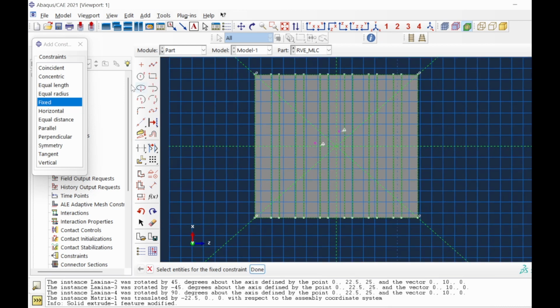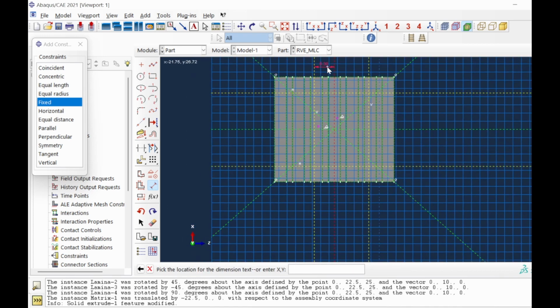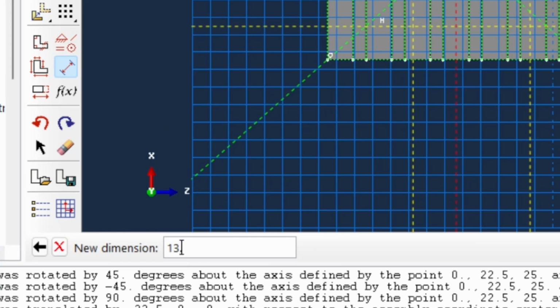Right. So what we're going to then do is to just randomly introduce some vertical construction lines. Vertical here, vertical there, and then maybe some horizontal ones as well. Horizontal there, horizontal here. But then we need to make sure that we have the right distances apart. So I'm going to have to dimension between here and that vertical line. So it should be 13.75 to give you the distances we are working with.